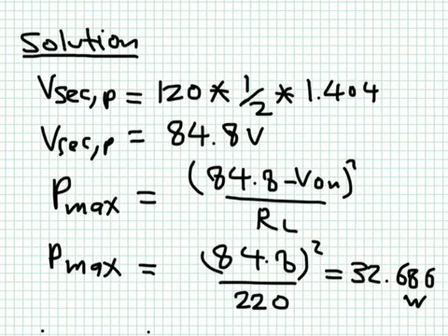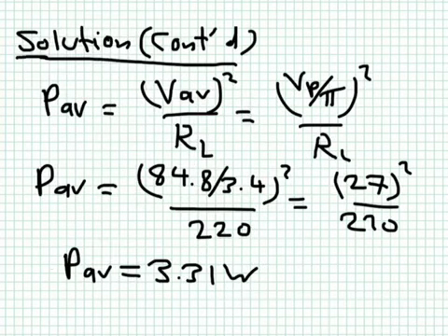But of course, as we agree, the power is really oscillating with time, because the voltage across the resistor is simply going up to a peak, and then it is 0 during the negative part of the cycle. To determine the average power delivered to the load, it is related to the average voltage across the load. We agreed that the average voltage will be equal to the peak value divided by pi. We derived that together. So you square that, and then you divide by RL. So you have to divide this peak value by 3.14, and I do not subtract V on here because V on is equal to 0. In other examples, if V on is 0.7, you have to subtract the 0.7 from this one.